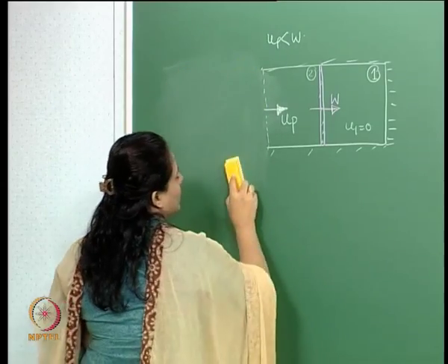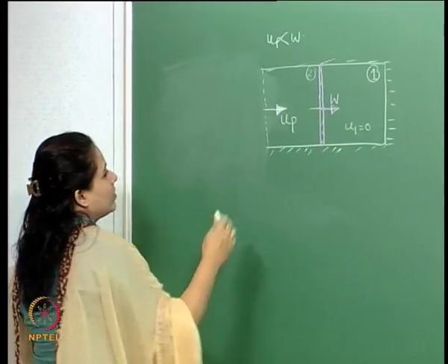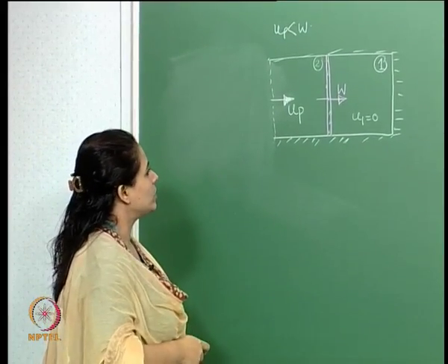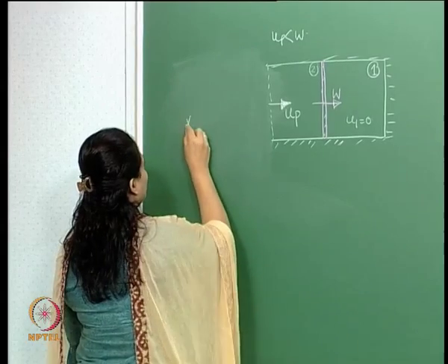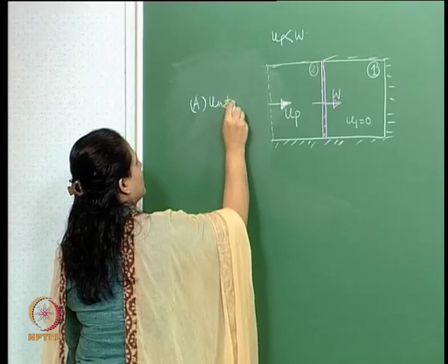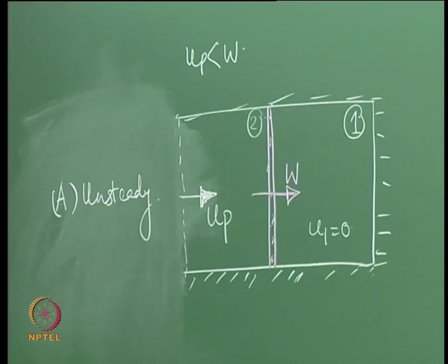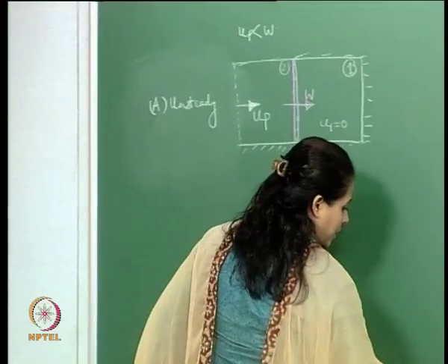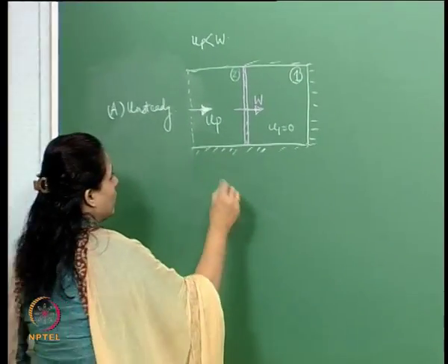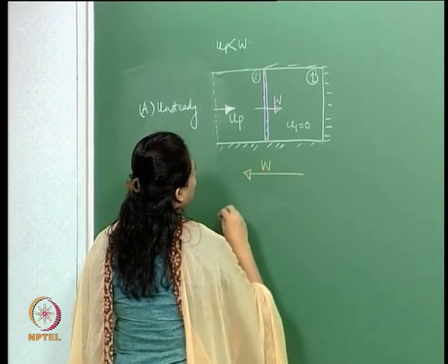We have a shock which is traveling to its right. This is the unsteady shock wave traveling. Now, if we have to convert this to the steady state case that we're most familiar with, all we will do is superimpose this flow with a velocity w in this direction.